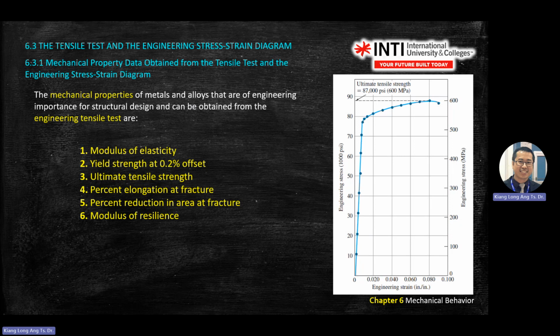It starts to show plastic behavior, meaning no return line, no return point. You reach the maximum that it can go. After this dot, it continues to stay at that shape already. Okay, so this is 0.2% analysis. It can be 0.1%, it can be 0.05, 0.001%. It depends on the accuracy of the data. If you go to nanostructures or nanomaterials, then this value will go further down.